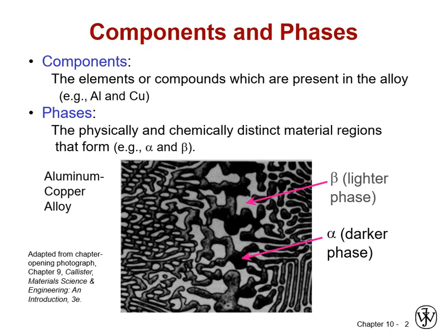In a precipitate, for instance, in our sugar, the boundary was the boundary between the solid sugar and the liquid syrup mixture. In the case of this copper-aluminum microstructure that you can see here, which is probably at fairly high magnification, at least 1000x, you can see that the optically distinct regions are multiple phases in the microstructure that have different compositions. The alpha phase is very likely to be an aluminum-rich phase, and the beta phase is probably an ordered intermetallic of aluminum and copper that'll function a bit like a ceramic. So they have distinctly different compositions, and they definitely have a boundary around them.